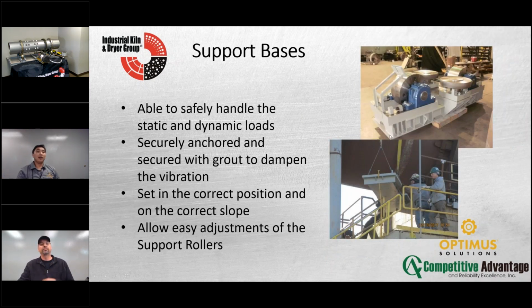Okay, so support bases. When we install support bases, if it's on a concrete pier, you typically want to grout under it. When we say grout, we mean the epoxy mix, and the idea is it effectively glues the base to the concrete pier. If you don't do that, ultimately, if it vibrates, and these will inevitably vibrate, it will loosen. You'll definitely have a lot of issues. And over time, it's going to loosen.